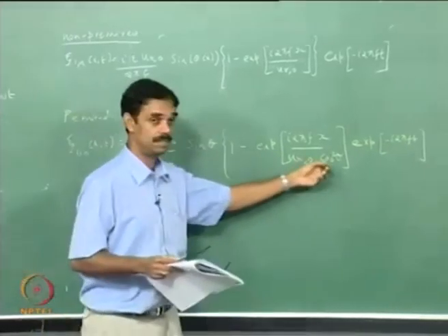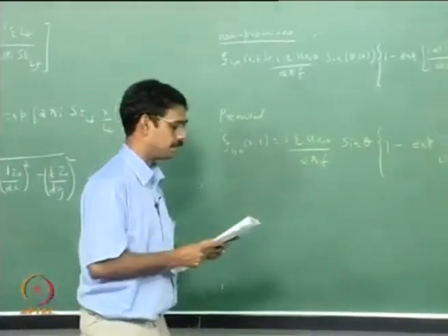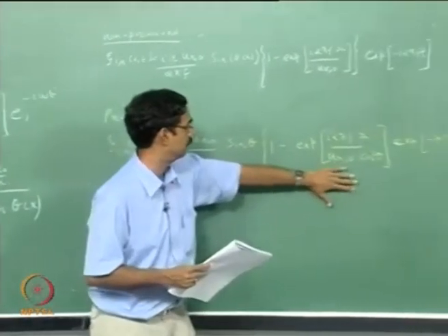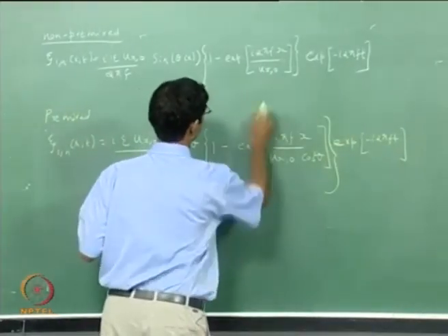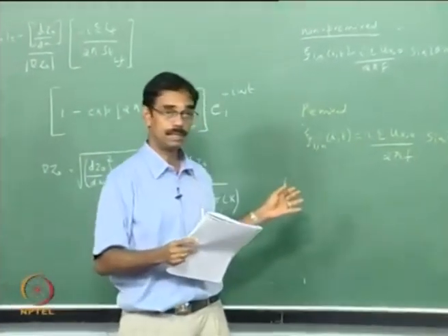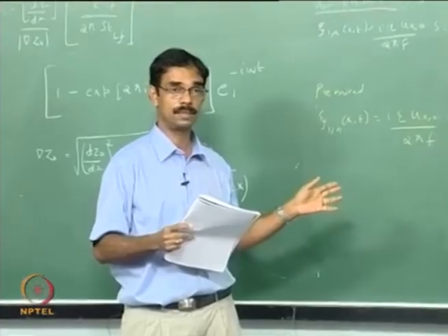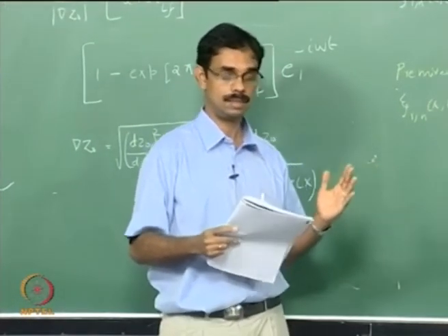So that is why you have this difference. In both cases you have local minima and maxima created through this term here and here, but the difference is because of the nature of the propagation of the wrinkles. In premixed flame the flame itself is propagating, whereas the diffusion flame just stands. Okay.